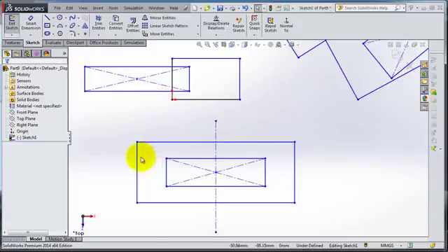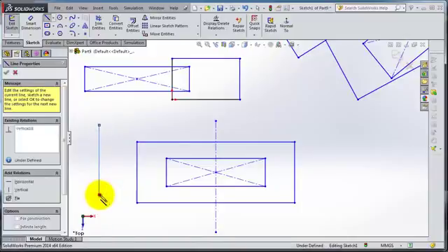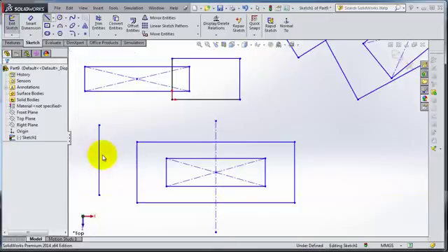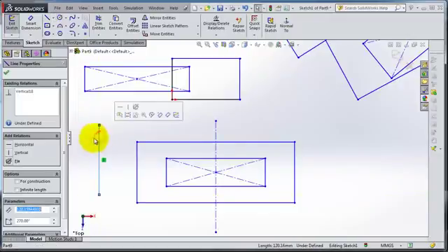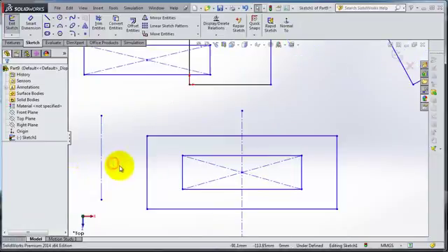And if you select one of these lines, or let's again select the line, make a line. Here in the options you have one for construction. If you select that, now you have a construction line. So this line can be used as a reference for your sketching and drawing as a helping tool. And also the center point can show you some references in your sketching.